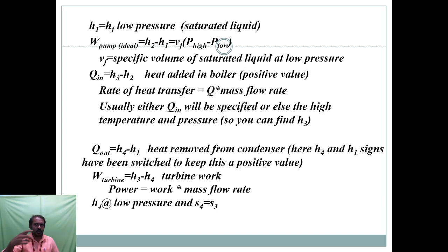The condenser is a cooling device, a heat exchanger. So the hot vaporized steam is converted to cool water. Steam is converted to water by the condenser, which is a heat exchanger process. After this the cycle is repeated. So this is the Rankine cycle.